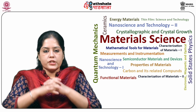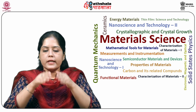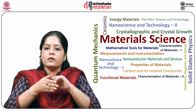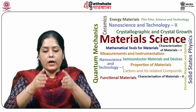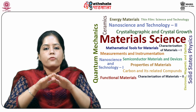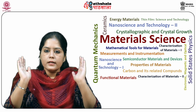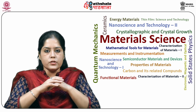Practical structure of JFET. There is a thin N-type channel that is laid on a much thicker P-type substrate that provides mechanical strength, as shown in this figure. As there is a PN junction between the channel and the substrate and channel and gate, it provides non-conducting walls to the channel as long as they are not forward biased by more than 0.5 volts. That is, when the channel is widest. The channel narrows when there is an increase in the reverse bias on either P region.